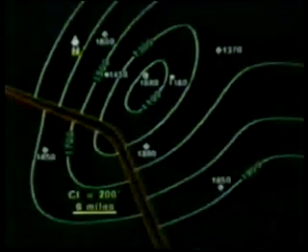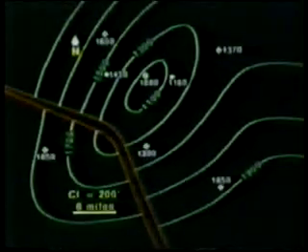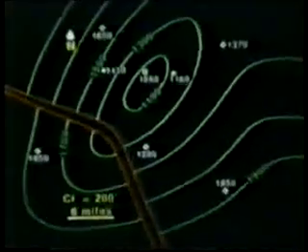In this map, the width of this gap can be determined by solving a simple structural three-point problem, since three wells, not in a straight line, have penetrated the fault plane at elevations of 1,900, 1,400, and 1,700 feet. In this case, the faulted control points all lie within the datum gap, but this is not required.